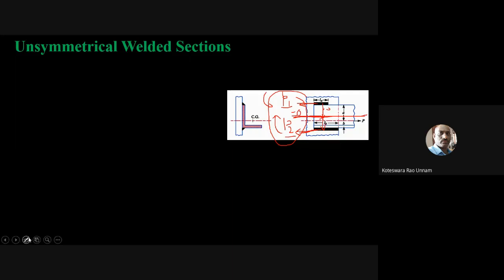In addition to the applied force here, this moment will create additional stress in the weld, which will decrease the strength of the weld. So in order to eliminate the bending moment, what they will do is adjust the center of gravity of the weld such that the bending moment created by the loads taken by these two welds is going to be zero.